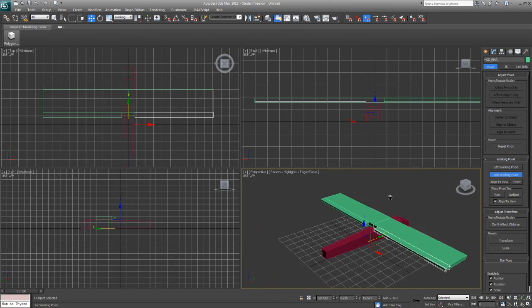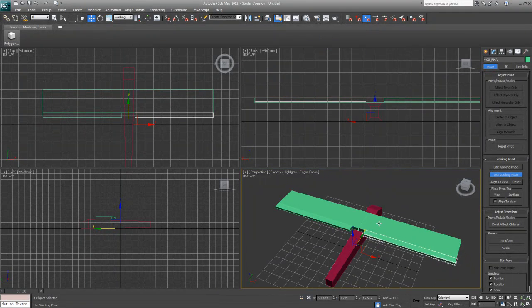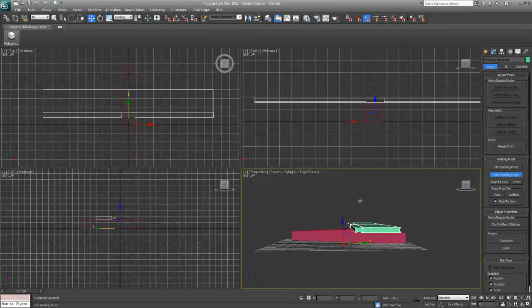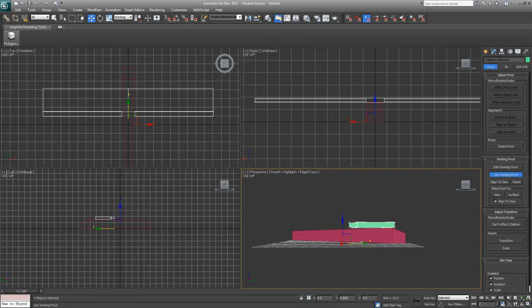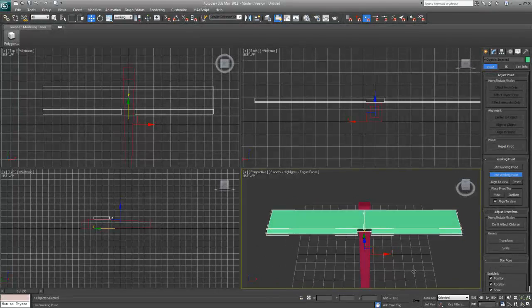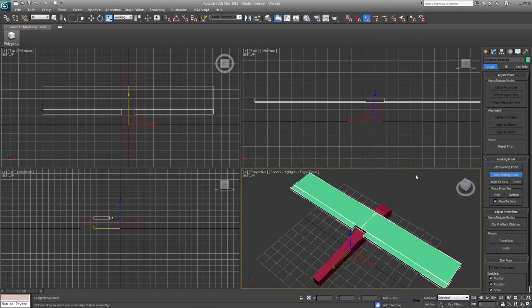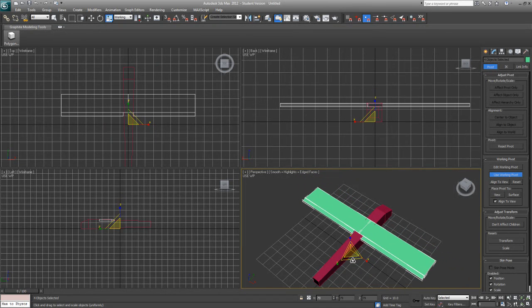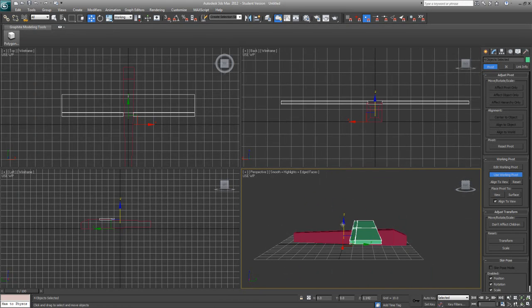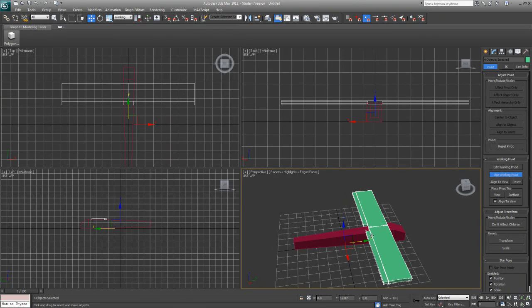Okay, so that's a nice big fat wing. Let's grab all these parts here. We're going to hold Control on the keyboard and click all of the wing parts, including the aileron. And let's position them a little more realistically. Okay, and I'm going to grab the scale tool, and if you hold the very center here, you're going to get the wing to scale in all its axes at once. So we'll shrink the whole wing down, and shrink all these parts together, and then switching back to the move tool, we can reposition again and get a more appropriate size wing.